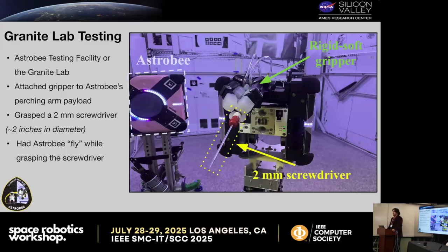How does your gripping compare to other gripping systems in terms of power consumption? Are they more efficient or less efficient? We didn't do a study of that, but intuitively, because we're doing less actuation on the fingers themselves, and it's all primarily in the pneumatic mechanism, it would be less power in terms of the torque needed than traditional rigid grippers. But there would still be a power cost to pneumatically inflating the gripper, which is higher in soft robotics than in rigid robotics. So intuitively, it would probably be around the same baseline.